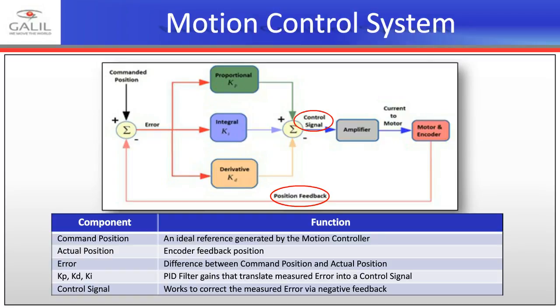In order to share the same voltage reference, they all have to be grounded together, which exposes you to ground loops, many other concerns. Wiring over long distances becomes problematic. Signal strength drops and becomes noisier. It's easier to pass a voltage across 5 feet of wire than 50 feet. You have to start taking into account wire resistance and things like that.